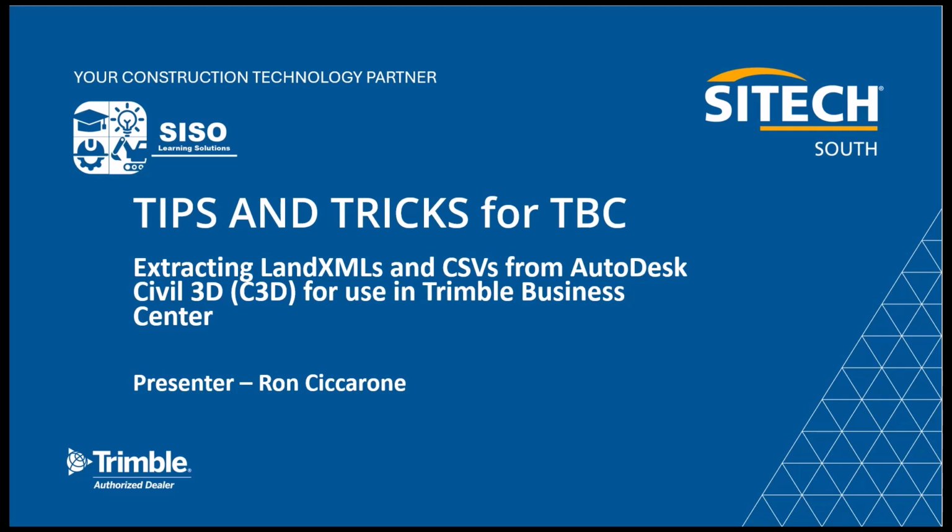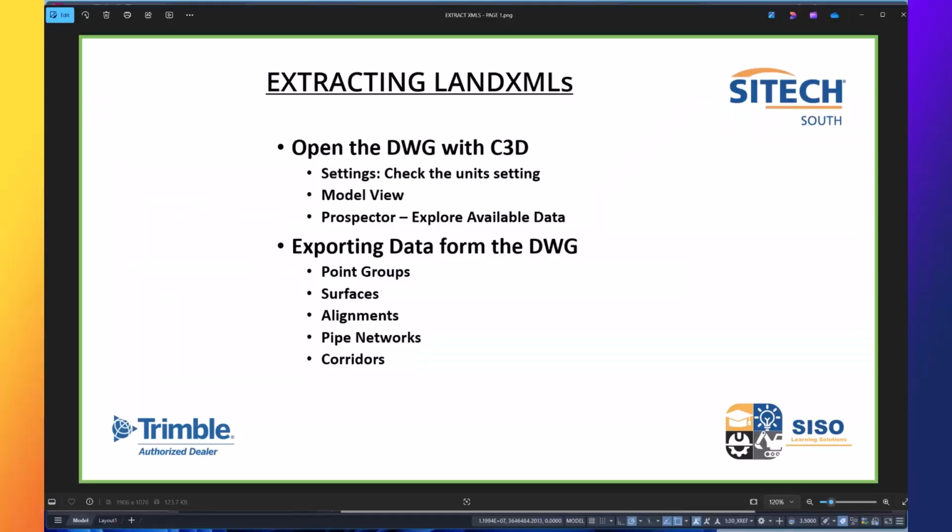In this routine, we're going to be extracting LandXMLs and CSV files from Autodesk Civil 3D files for use in Trimble Business Center. I'm the presenter, Ron Ciccarone. The initial part of this tip and trick video, we'll be working in Civil 3D, showing you how to extract the LandXML data. And the second part of it will be in Business Center, showing you how to import.